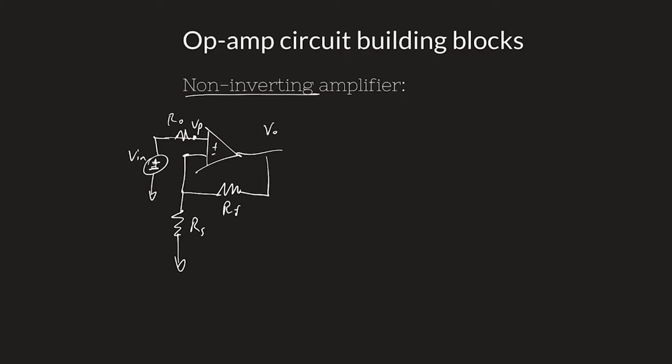The trick to analyzing these circuits is to realize that you never have current going into the op amp on the inputs. So these are always zero. Call this Vn. With those being always zero, if I arbitrarily label a current going this way, I could have labeled it going the other way, it doesn't matter. Just choose a direction and go with it. The numbers will work themselves out, positive or negative, however they're supposed to, based on the values you choose.